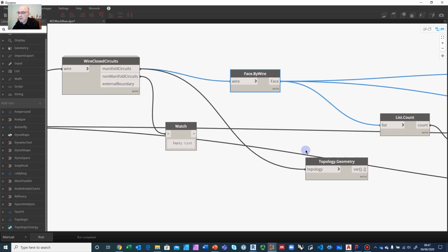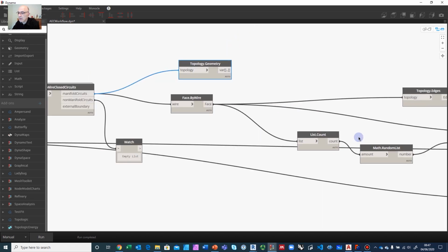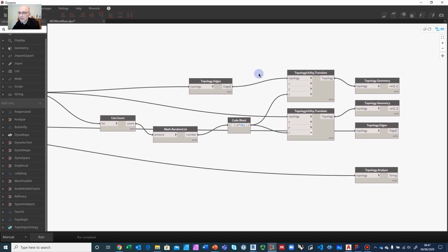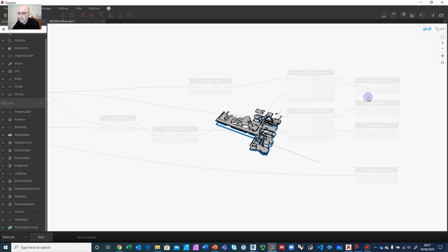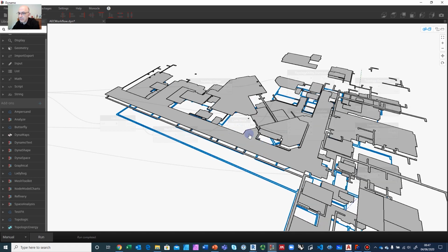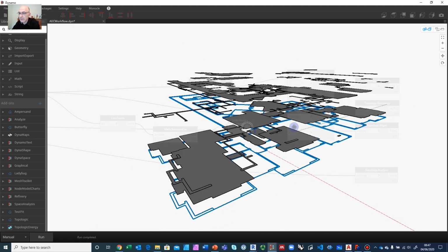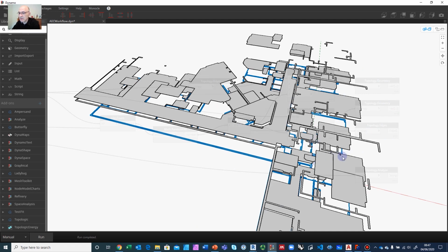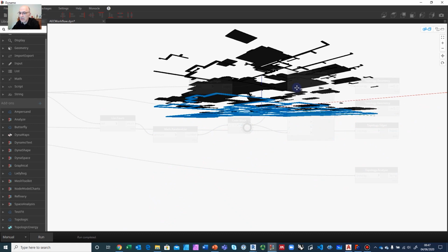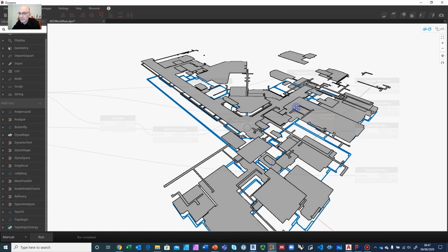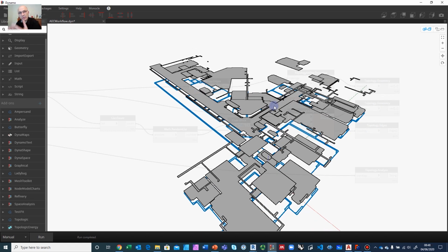So I create a face by wire. I draw them as well, and then I randomly offset them up in the Z so that you can see them. So this is what this is all about here, and I draw the edges. So let me show you the drawing of it. So here it is, and everything is in there. So this would be really very good for moving this forward, extruding it up, or even laser cutting it, because these are all separate pieces now. So you can even build a model out of it. And what you see at the bottom is the actual raw data, the actual wires that came in. So this is from AutoCAD all the way to something that you can build three-dimensional entities out of, and build also topologies, so adjacency information will be now easy to obtain.